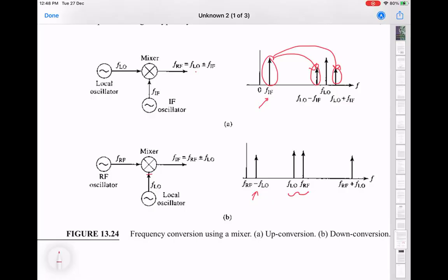Okay. Yeah. We use down conversion in a multiple system. We send IF frequency to one port, and the same IF signal can be sent to the other mixer, or we send IF frequency separately to all the other mixers, the multiple mixers. No, I mean, that depends on what you're trying to do. Here, I'm just right now only telling you that the same mixer can do both up conversion and down conversion depending on what ports you're exciting it.